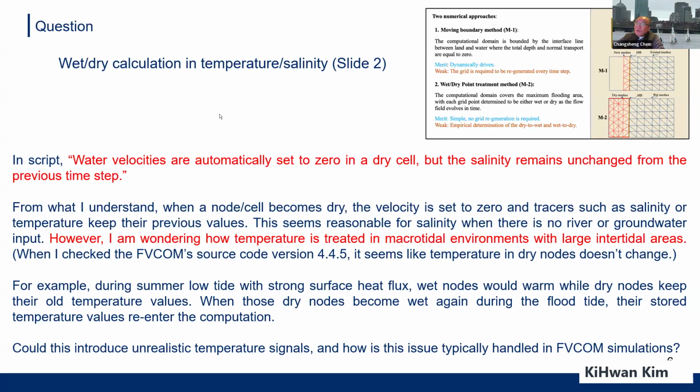So you put heat on, and you can get overheating or overcooling, because it's dry and not being calculated. That's why we put the initial temperature there, to make sure when you do the temperature calculation, the temperature in the dry region is assumed to be the previous temperature. This way you don't get a big jump in temperature variability, right?